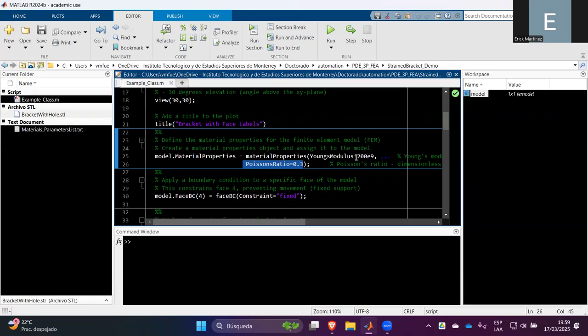And also, I wanted to mention that the units in which you need to express, for example, the Young modulus should be expressed in international units. Okay, so in this case, I am assuming that this value is in pascals. You need to be very careful about that because MATLAB will assume that all the operations will be performed by considering international units. Okay. So we can now execute this block of code by pressing the Ctrl and Enter keys on your keyboard.